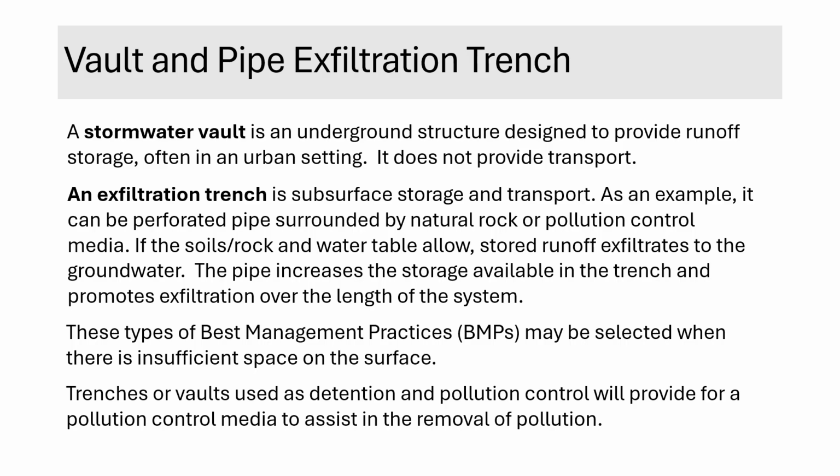Both trenches and vaults can be designed as either detention or retention systems. When used for detention, they help control peak discharge rates by attenuating the hydrograph, essentially slowing the release of water. When used for retention, they allow the stored water to exfiltrate into the ground below. In either case, pollution control media can be incorporated into the design to help remove contaminants from the runoff before it reaches the groundwater or downstream waterways. These types of best management practices are typically selected when there simply is not enough surface area available to accommodate